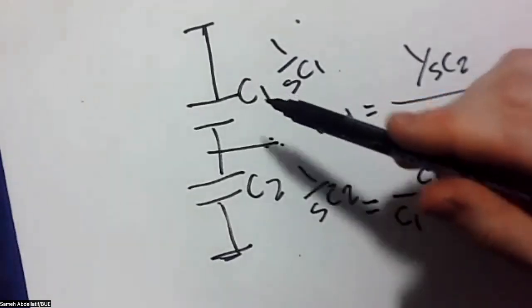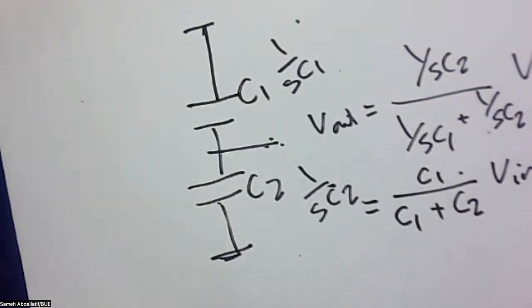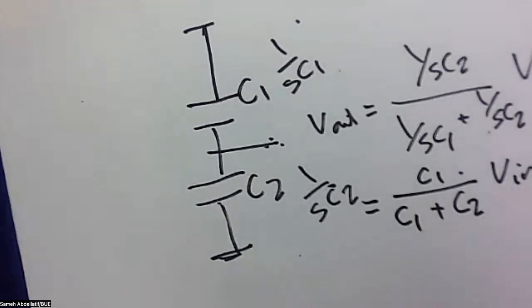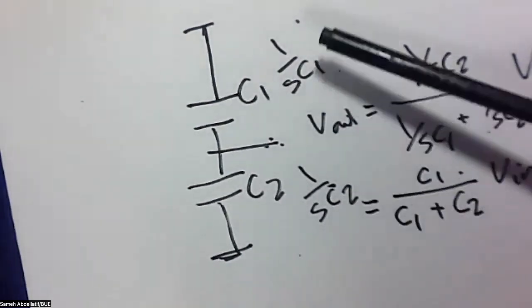So if C1 or C2 is a variable capacitor or a piezocapacitive sensor, whenever the capacitance changes, so for example, if we consider C2 as a piezocapacitive material, whenever C2 changes, the output will change accordingly to this equivalent value for C2 and so on. So this is a model where you can use this capacitance divider in order to vary the output. But here we have to consider some very important points. The first point is, as you already typically know, capacitance can only have this capacitive effect or impedance effect far from DC, because simply if you substitute here with omega equals to 0.